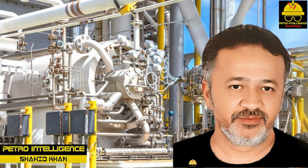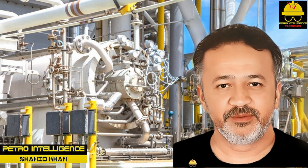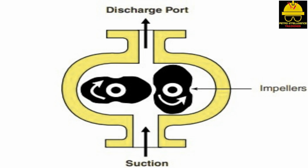Lobe compressors. Lobe compressors are characterized by the two kidney bean-shaped impellers used to trap and transfer gases, as shown in the picture. The close clearances between the casing and impellers are maintained by a set of timing gears. During operation, the two impellers move in opposite directions on parallel-mounted shafts as the lobes sweep across the suction port. The parallel shafts are composed of a drive shaft and an idler shaft.